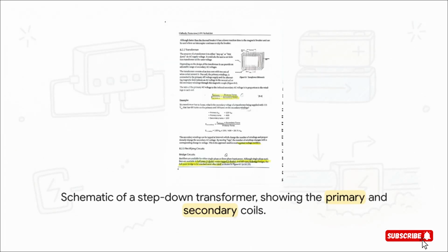Next up is the big guy, the heart of the unit, the transformer. Its main job is to take that high voltage from the power line and step it down to a much lower, safer AC voltage. It does this with 2 coils of wire, a primary and a secondary, wrapped around an iron core. It also provides electrical isolation, which is a really important safety feature that keeps the high voltage grid separate from our cathodic protection circuit.